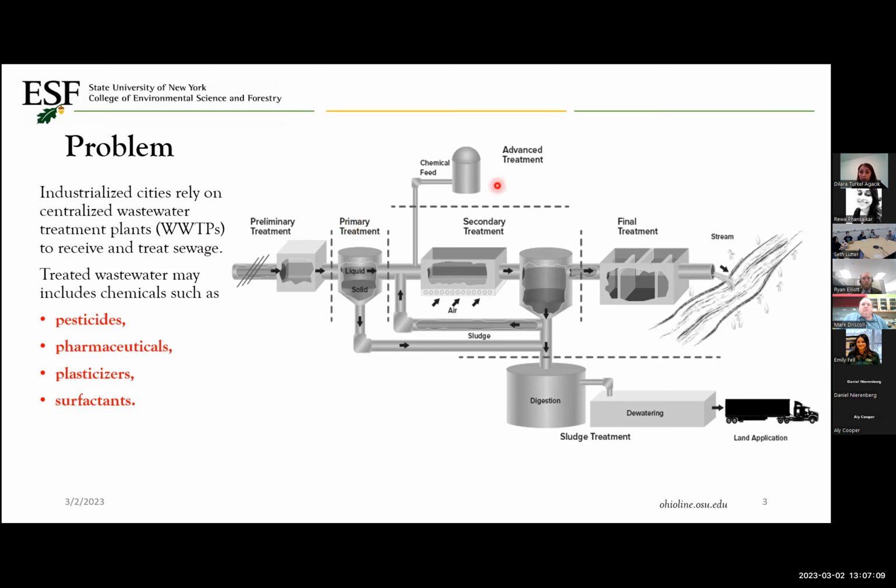And in the secondary treatment, which is also known as the biological treatment of wastewater, microorganisms are used to purify the water. The purpose of the final treatment is to kill disease-causing organisms, which is the last stage of the wastewater treatment. In this stage, chlorine is mostly used as a disinfectant to kill disease-causing organisms, but because the chlorine is toxic,